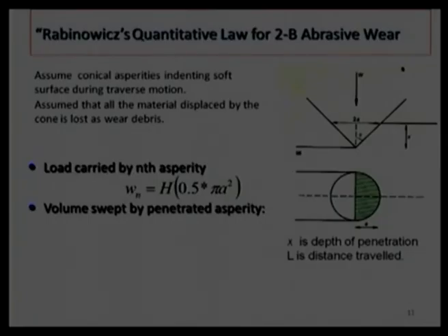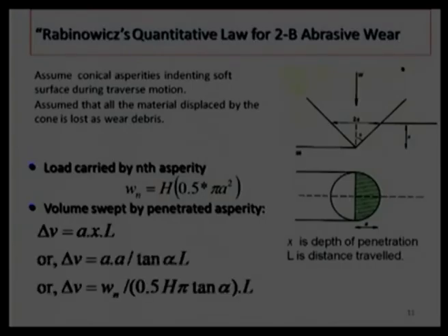We want to find out how much wear will occur on that surface. So, in that case we need to find out what is the swept volume, how much volume has been displaced. That can be figured out from the radius, distance which is traveled L, and depth of the penetration. So, depth of penetration is x,